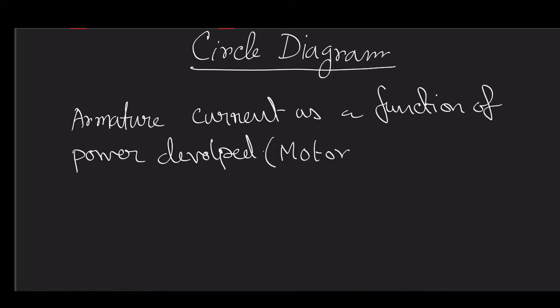As we know, we are considering balanced steady state operation. During that, if we disregard the constant losses, like I have explained in the video, then the per phase power will be something like VI cos theta minus I square R. Correct. Now, this is the amount of mechanical power developed.